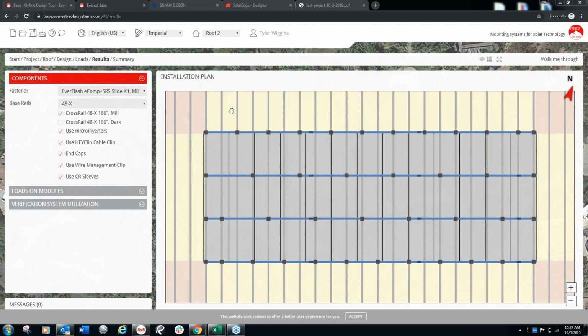So what I would recommend doing is consulting with the engineer of record on the project, drawing that rectangular shape. Maybe you're drawing it over that polygon roof, and then consult with the engineer of record on the project. They have the final say, I should say, on where they want those attachments placed. If there's some corners of that roof they feel are going to be in higher load than others, that may not be represented best by a rectangular roof drawn on this tool.